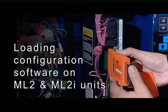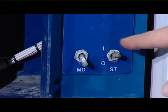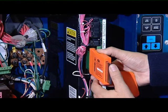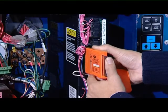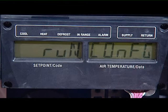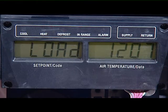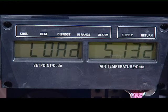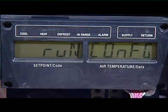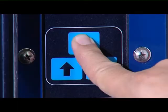Loading the configuration software on ML2 and ML2i. Switch off the unit and insert the adapter with the card. Switch on the unit. The card contains the following files: the configuration file, software number 1207, software number 5132. Using the arrow key, select the configuration file and press the Enter key to confirm. The display will show once again, Press Enter.